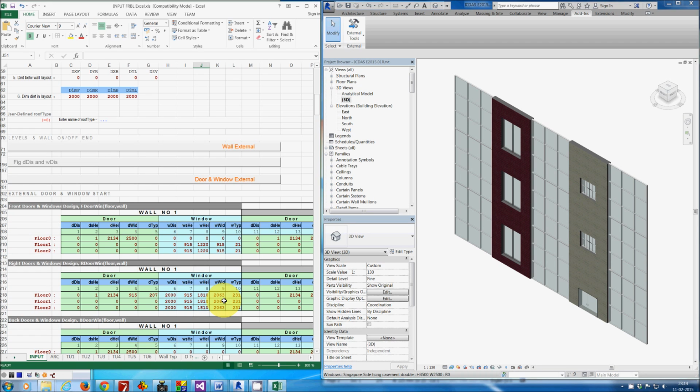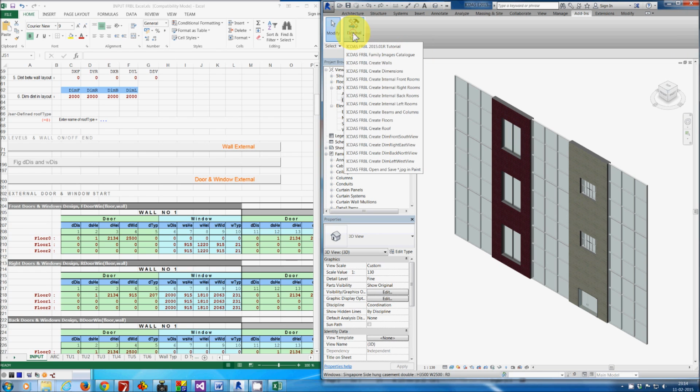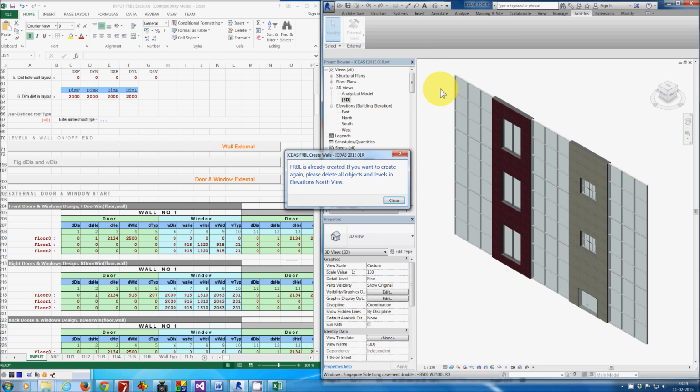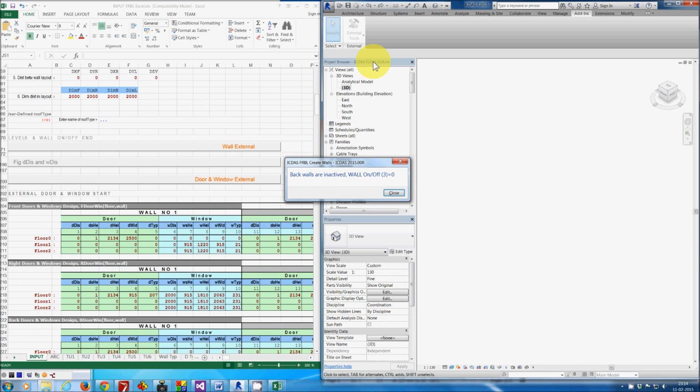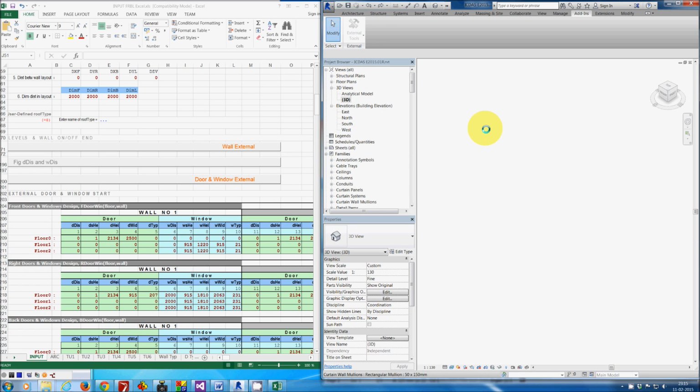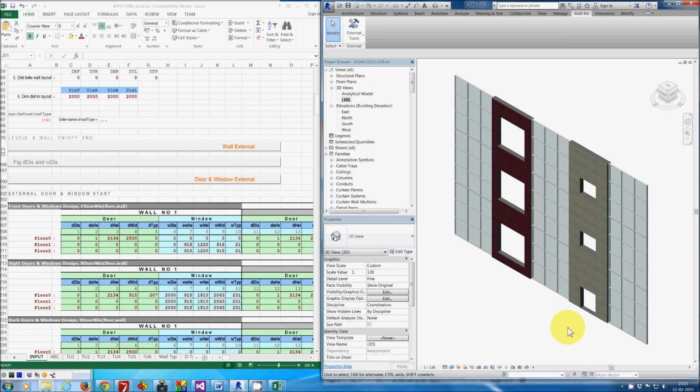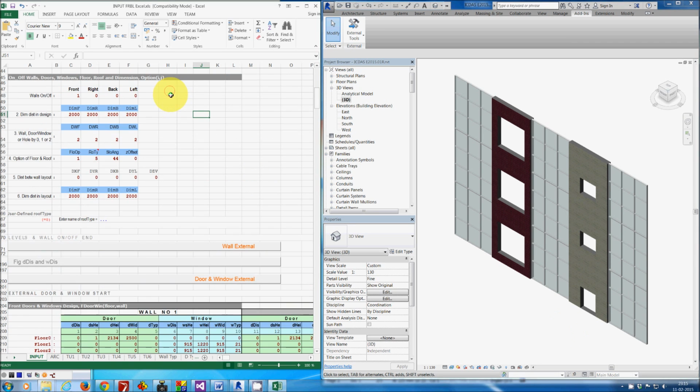In case you are in production, you just deliver the wall with a hole, so just enter the dimension of the hole here. So I press Ctrl Z and create wall again. So it creates only the hole. I have also dimension correct in the 3D order, so I activate it now.